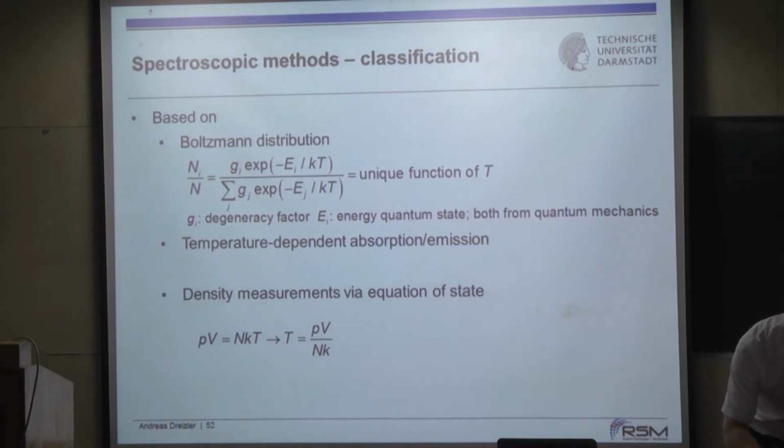One possibility is you just take a bubbler. You have here your toluene. It's a liquid. Then you bring this into, this is at a certain temperature. You fix that in a bath. Yeah? This is isolated as well. You bring in your nitrogen. And here the nitrogen bubbles out, and here you collect it and bring it to the engine. And then you should be sure that afterwards the temperatures are higher to avoid any condensation. But if you do that and you have the saturation value reached, maybe you do it here for 290 Kelvin, and starting from here you have 300 Kelvin, you're fine, but then you have reached the limit.